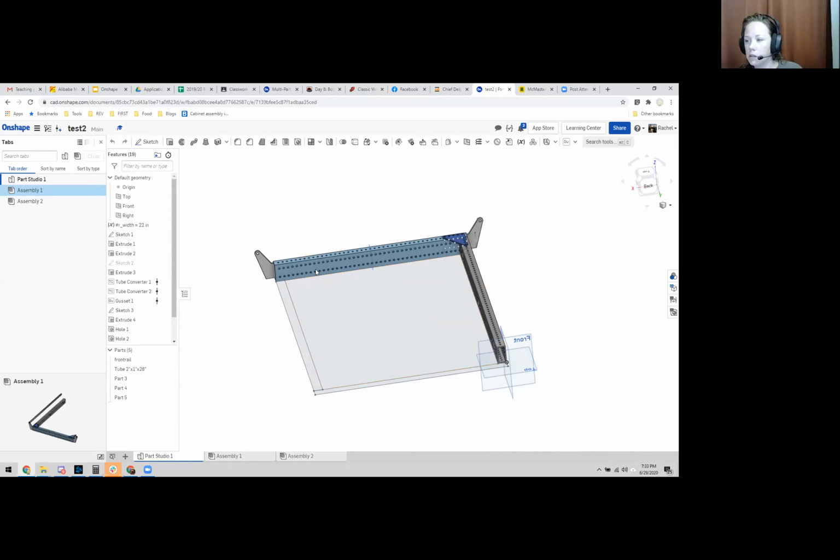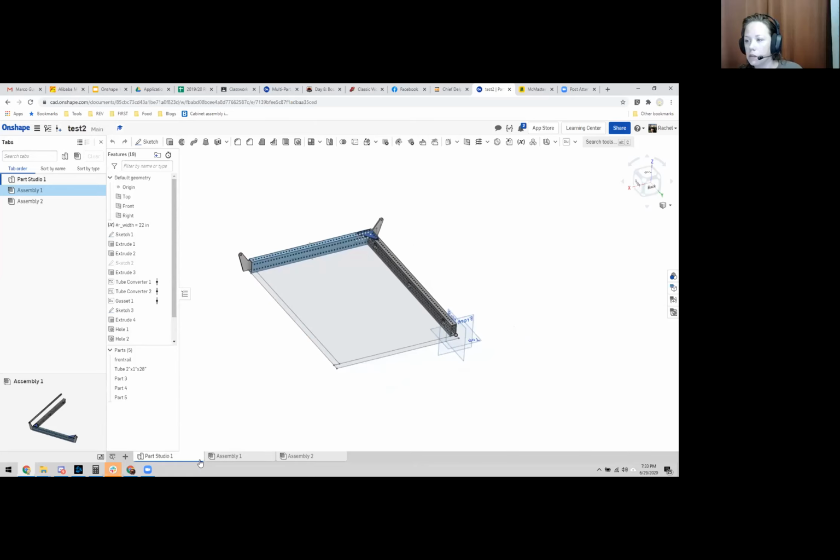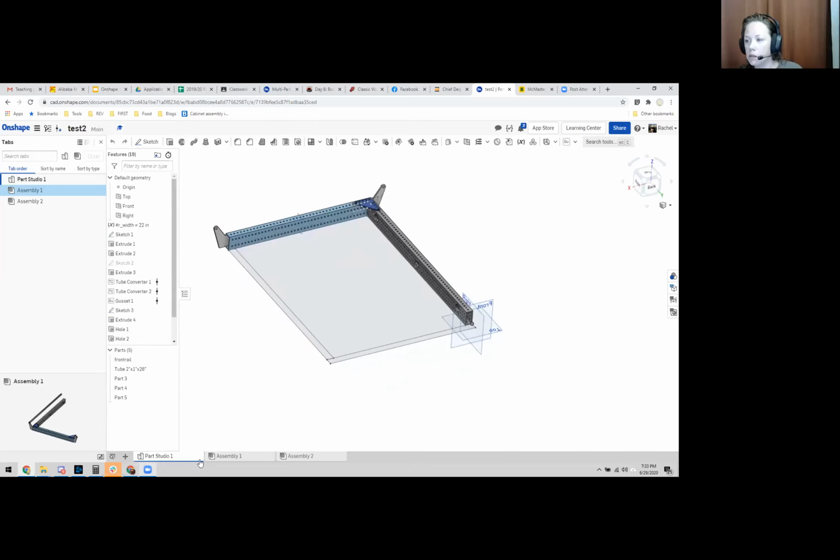If you're using CAD to keep really good track of your BOM, for the parts that are the same, Onshape won't know that they were the same. It'll just list it as a discrete part. So how it's handled on the BOM side of things would probably be not ideal for people that are really relying on that BOM for manufacturing.